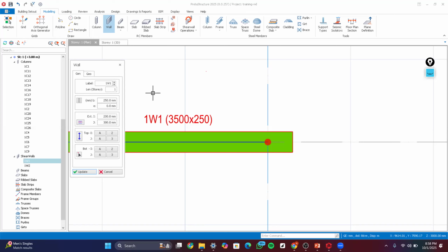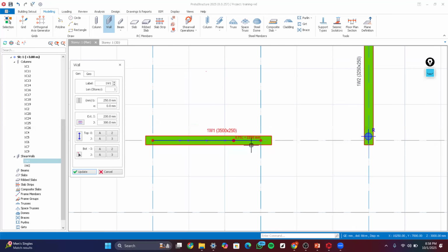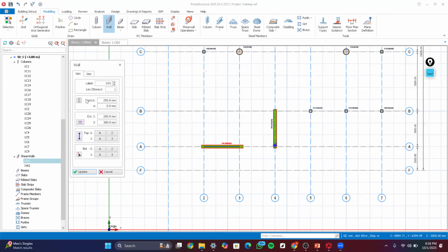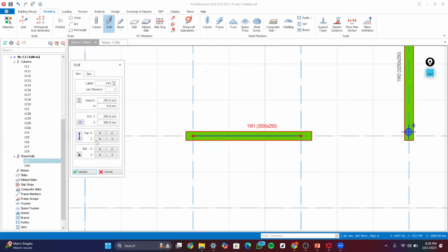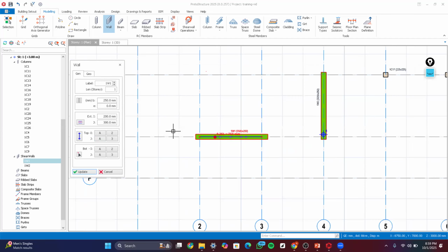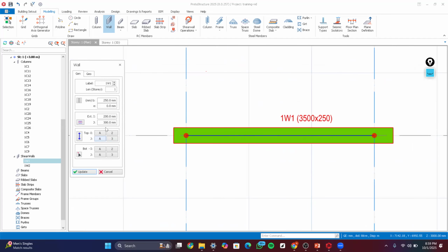So moving on, that is simply how to create your walls. Then we have this option that says top I and J. This top I and J is simply the axis placement, the axis intersection, which was used to place this particular wall. When you select one, you're going to find all these properties. So go to geo, which simply means geometry. So we have the plane top and bottom options. These plane options are actually used to adjust the elevation of the wall.